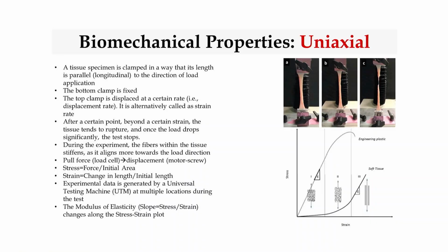So typically a test specimen, you can have the test specimen in the form of a rectangular specimen which has a certain depth or thickness, that is typically the norm, or you could have a specimen which you can cut in the shape of a dog bone. These are typically not possible that much for soft tissues which are extremely soft. For metal specimens, in mechanical characterization studies, they're usually in the shape of a dog bone, and that's there for a reason, right? This is for the nice and uniform stress distribution.